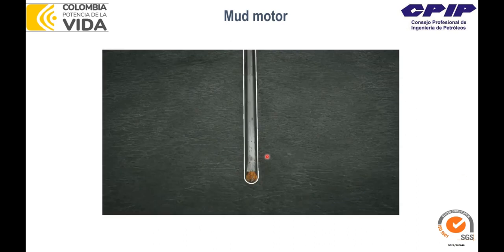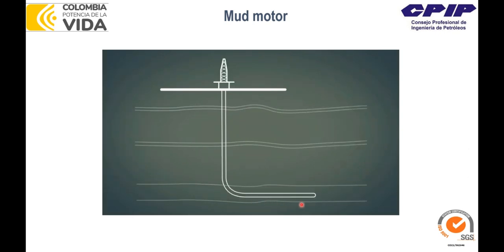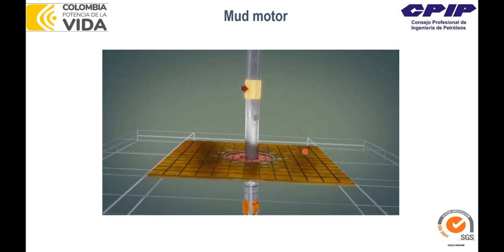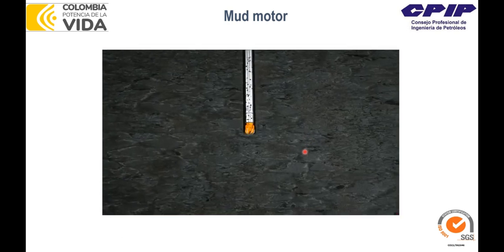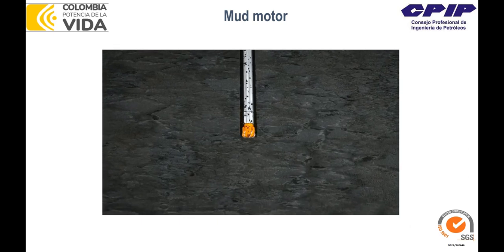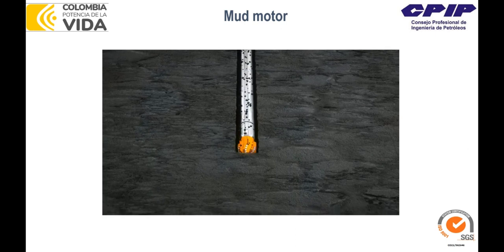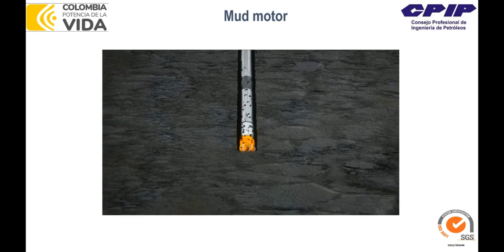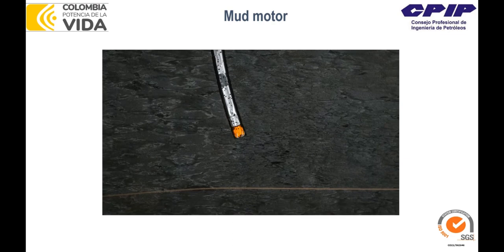Mud motors can be configured for every section of your wellbore: vertical, curve, and lateral. At the rig location, an adjustable bend housing enables changing the bend angle, which modifies the build rate the motor can achieve. The performance motor application saves wear and tear on the drill string in the vertical hole, and it allows for increased ROP. When you reach the kickoff point, a stabilized steerable motor with a higher bend enables faster kickoff from vertical when drilling the curve section of the hole.